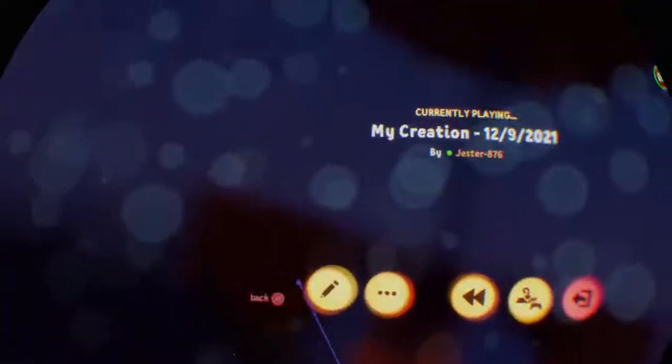Alright, so we will twist 90 degrees. So much easier with the grid on. Always turn the grid on when you're doing that. And then just bring that and watch that green line so that you're not moving in this dimension at all. And then you can bring it straight down under and you know that it's good to go.